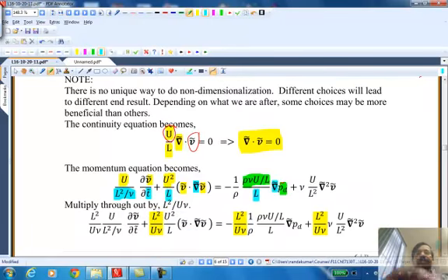And the last term is v gives rise to u and del square. That's a Laplacian operator, right? So that will give rise to L square in the denominator. Okay, and nu already exists. So now I have made all the terms dimensionless, but every term has a factor in front of it, which consists of constants. Okay, and the actual terms are dimensionless now.